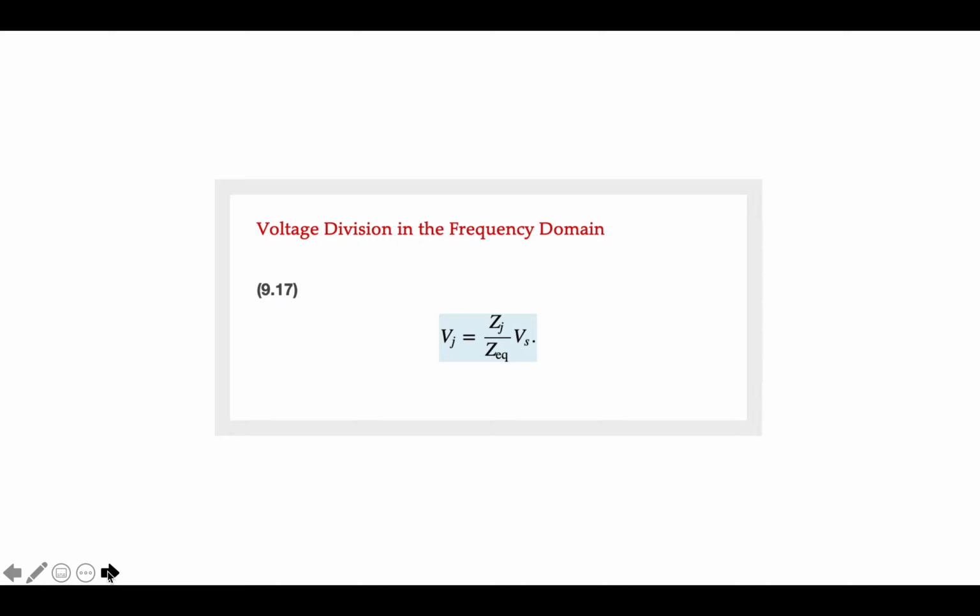Sometimes it's easy to talk about admittance when you're talking about capacitance, because then it becomes j omega C for the admittance rather than 1 over j omega C for the impedance. There is going to be an example in this series of lectures that works with admittance. As a general rule, in this class and in Circuits 2, that's not something that I really work with much. So we'll show the example, but you can just as easily do that with impedances.